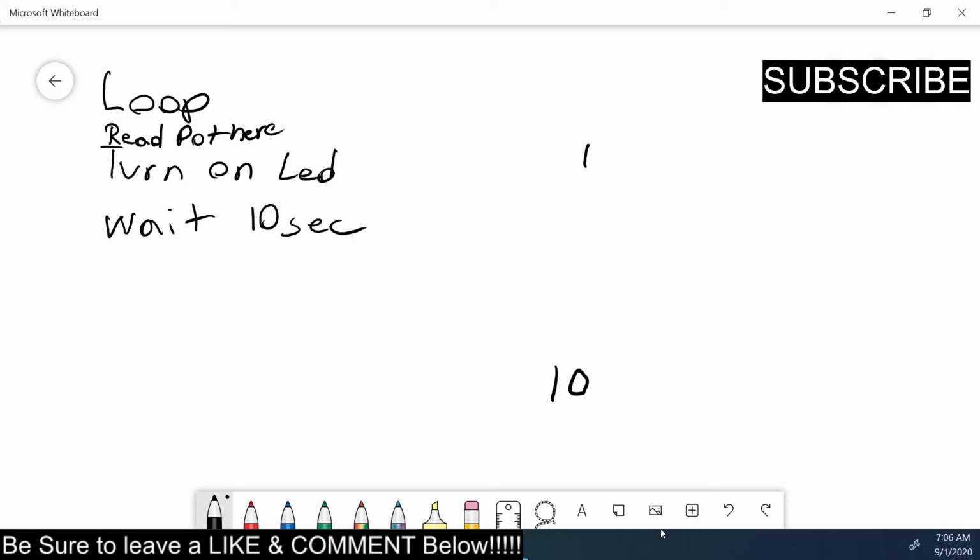But then if I change it in the middle of this 10 seconds, it won't change, because it won't read the potentiometer again until it goes through the loop and back up to read potentiometer. So you can see where this comes into play.